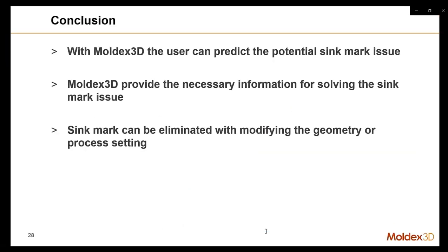So today we talked about the seam mark, and first we talked about what kind of locations will generate the seam mark, and we offered several ways to help you deal with seam mark. And we also showed you some examples to show you the capability of Moldex3D. Moldex3D can help you to predict the seam mark and can help you to deal with seam mark in a virtual environment.